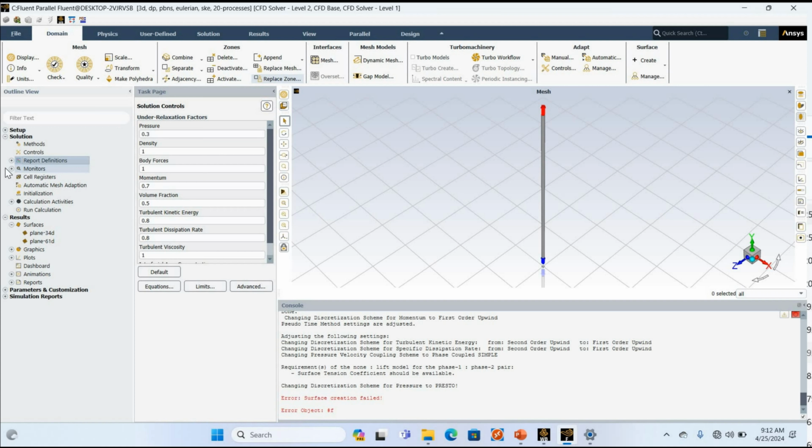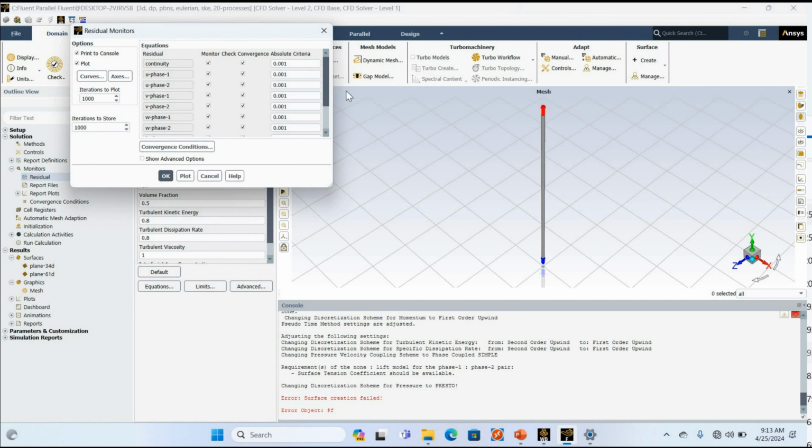So there is another method, like if your simulation is running, you can see your results from the control plots during simulation. That is actually a trick, a shortcut to see your results, how it is going. For this, yeah, you need to create a control plot. Okay, monitor, we can do this later, but first we need to specify the convergence criteria.